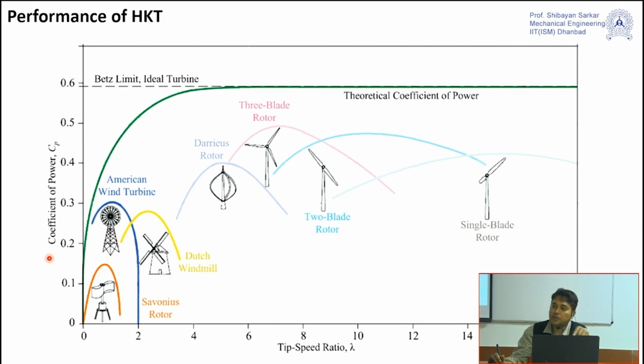Since I cannot ensure a constant speed of the river flow, I also cannot ensure constant rotation in this turbine. So the frequency of the electricity generated through this turbine will also fluctuate. You have to consider all those things, and accordingly choose your device so that ultimately a constant frequency can be given to the consumer. This type of modification is required for this type of turbine.